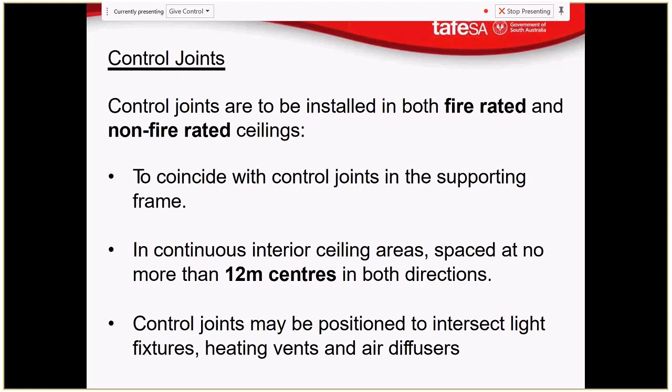What we would prefer in this scenario is to have it flushed and then have a very fine cut placed in here, so that if there is any separation, it separates in a very smooth, nice, straight line, which can open up a little bit and be imperceptible, or close up a little bit. So to mitigate our crazy cracking.